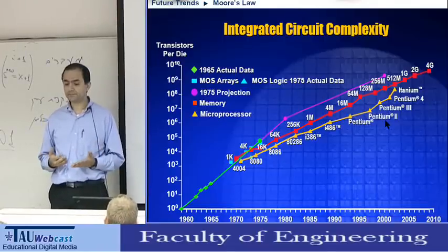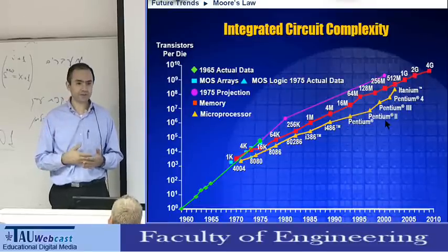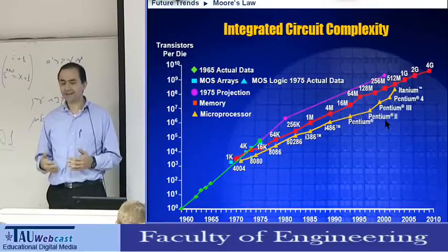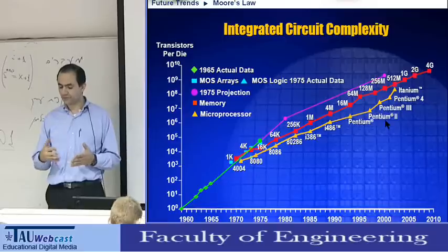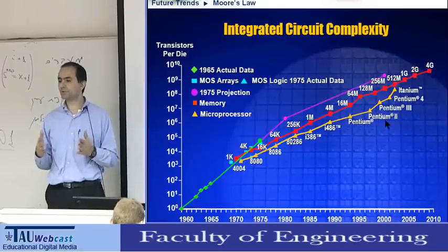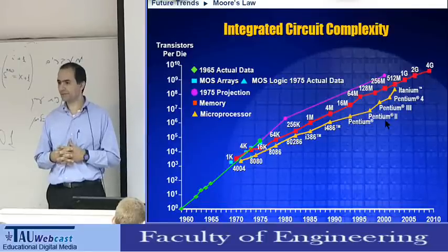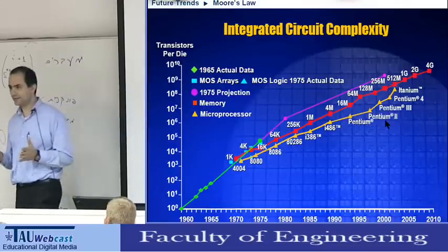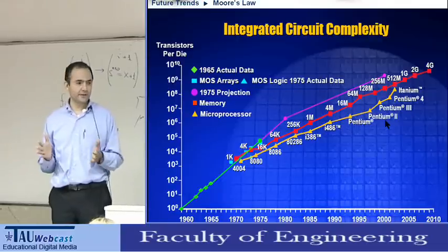So there is an expectation from the industry to the manufacturers of lithography tools to be able to produce, every 18 months, a lithography tool which enables shrinking the line by a factor of 0.7. So the area shrinks by a factor of 2. Okay? So every year and a half, we get a shrinkage of the area by a factor of 2.